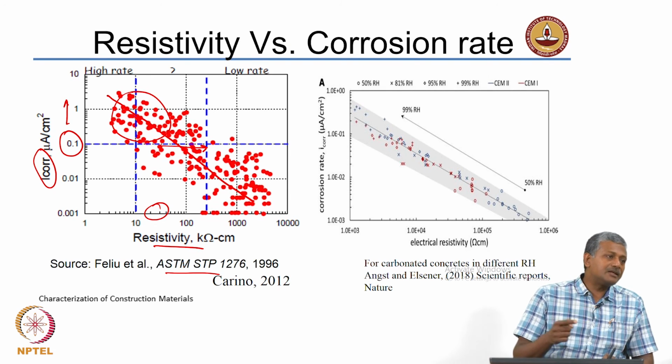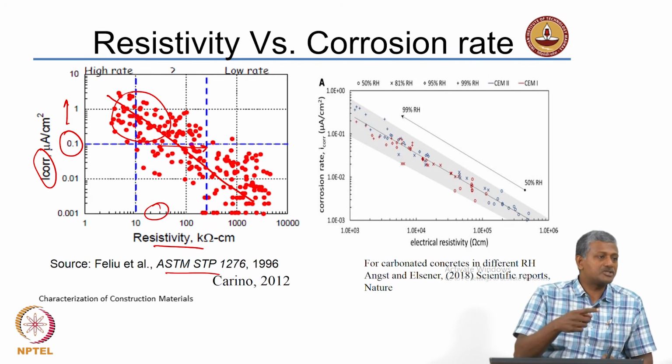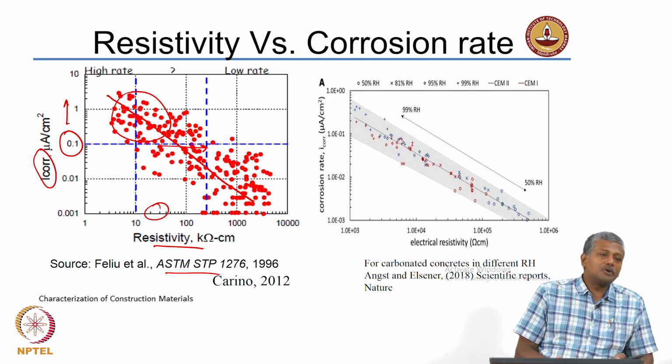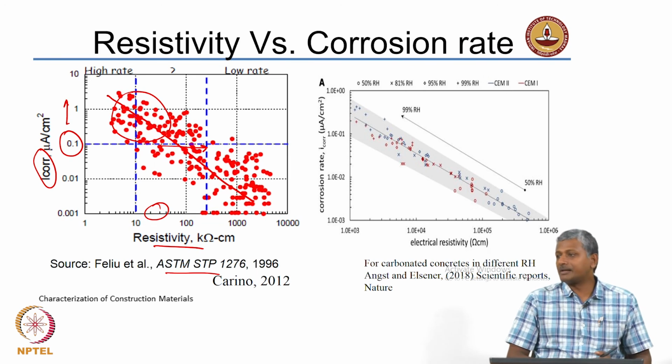Your resistivity indicated by the experiment will get reduced when steel is present in the vicinity, because the charge is getting carried much more easily. So, because of the presence of steel, you will actually show a lesser resistivity in your system. So maybe you can say that it is a more conservative approach to have the steel inside.